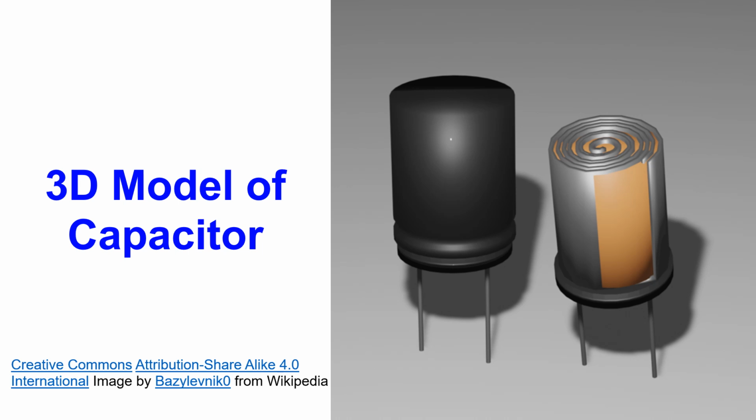Though electrolytic capacitors have very high capacitance, they have poor tolerance, high instability, gradual loss of capacitance, especially with high ambient temperature, and high leakage current. Electrolyte leakage from poor quality capacitors could damage the printed circuit board as well. There could be self-degradation if left unused for a long period, like a year, and might lead to short circuit when full power is applied.